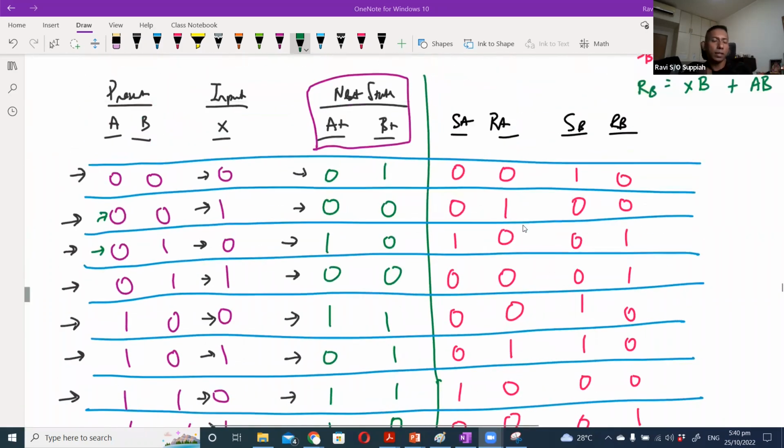Okay, to put it clearly, practically speaking, when you power up any circuit, you cannot guarantee a default state. That is why, if you look at most of your combinational circuits or sequential circuits, there is usually a reset line to bring everything to a preset starting point.